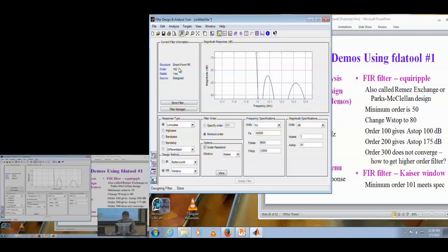Yeah. So are all of these iterative? Kaiser's not iterative. Kaiser's a formula. Parks-McClellan's iterative, and least squares is not iterative, but it requires a matrix inversion. So it's a formula, but it's a matrix formula. This one is a scalar formula for Kaiser.